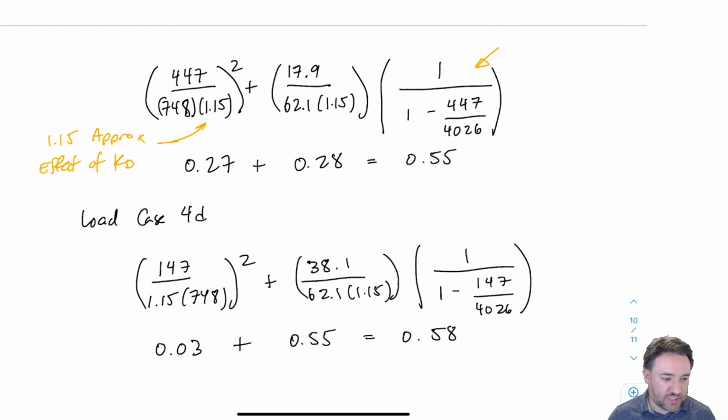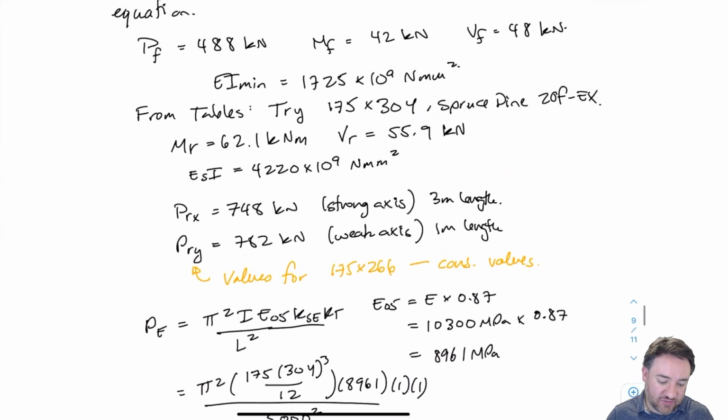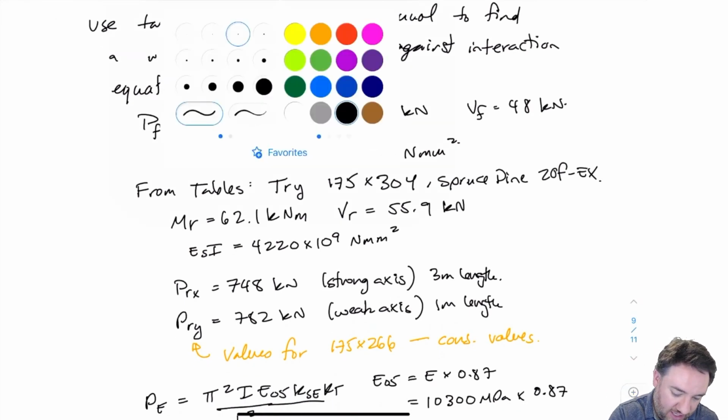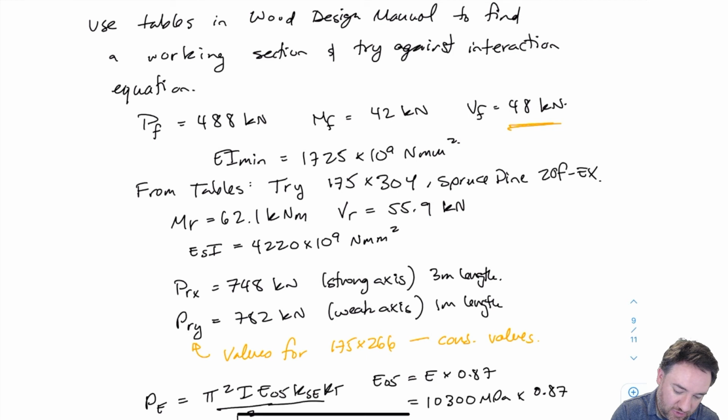I'm only using 60%, but remember that in terms of the shear strength, I am pretty close, right? And that is basically what governed our selection of this member, because there's the shear force and there's the shear strength, and they're pretty close. And that VR does not yet take into account the fact that we have a shear notch cut out of the member. Okay, so I'm going to put a cut in here. And in the next video, we're going to start checking everything for this selection.